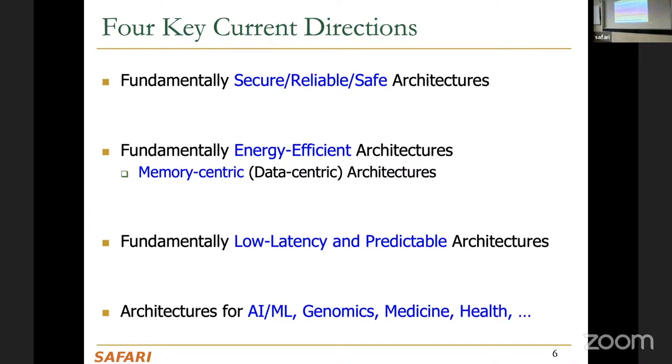This is why hardware is so important, I think, in terms of security, right? Your trust is built on the fact that you cannot expose a secret key to someone. But if someone figures that out using side-channel analysis, like power analysis or some other side channels that exist in the processors, or RowHammer, actually, people have shown that, basically different types of vulnerabilities, then your trust is broken.